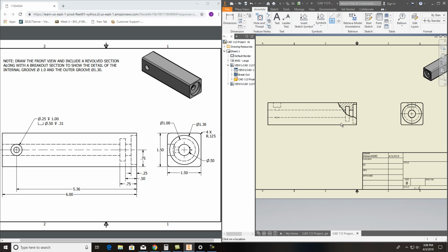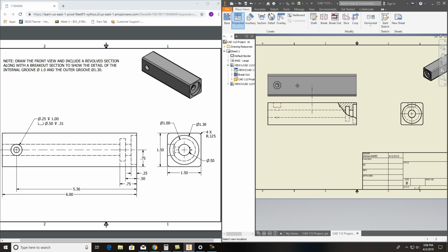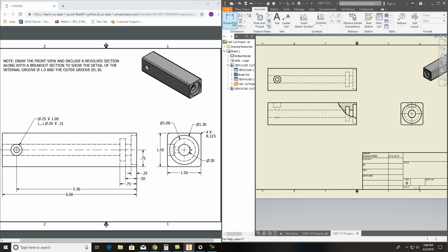And I'll be honest with you, I didn't draw this one, I didn't put it on our sheet exactly. You'd have been better off if you would have taken and had this to where you could see it, but we could still do a projection, because I want to see this hole straight on. I could project it up just like that, which would be great too. We could always do that. So that way I can document this hole here by hitting on the hole command and come up here, and we'll have all that information too.